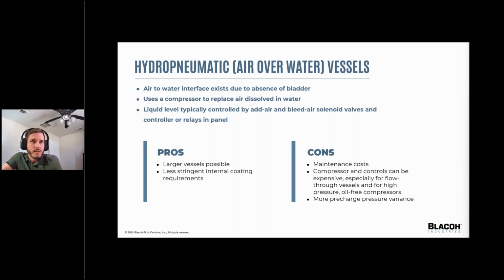Some kind of liquid level measuring device is used, whether it's guided wave radar or level switches or differential pressure transmitter, etc. A controller or relays are used with or without delays to determine when to actuate solenoid valves. The compressor is sized to keep up with the dissolution rate. Typically, the governing criteria is that it must be able to recover a lost charge in a specified time frame, usually minutes after a return from a power failure.